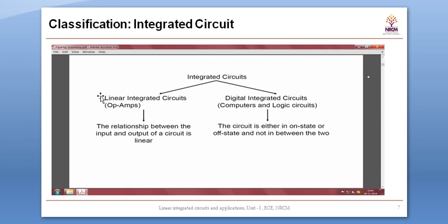You can easily identify the linear integrated circuits. For the applications of the ICs, if you are using external resistors and capacitors with the integrated circuit, then that integrated circuit is a linear integrated circuit. For op amps, if I am interested in fabricating an integrator application, then I have to attach the resistors and capacitors outside the IC. So that's why the IC 741 is a linear IC.